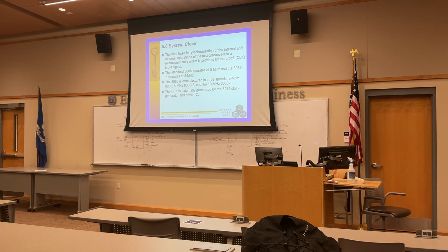F0 is equal to 1 over 2 pi square root of k over m, where m is mass. So if we use it to make a vibration, this cycle, this period is well-defined. It's very repeatable with very small error.